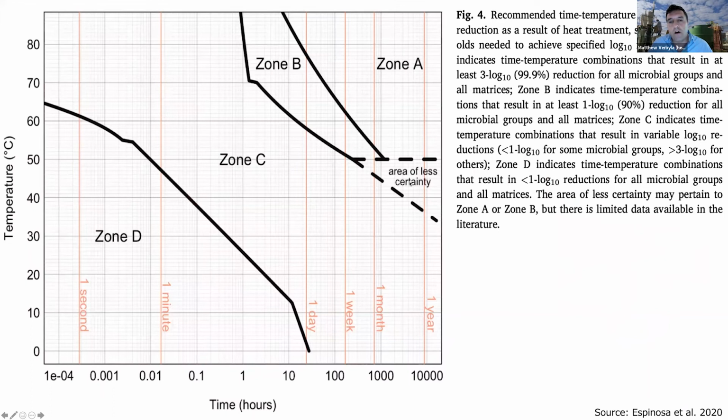So in order for all pathogens to effectively die off in a pit latrine, you need to achieve a combination of temperature and holding time, which can range from minutes to days to weeks to months to even years, depending on the pathogen type. So some pathogens, like bacterial pathogens, might die off more quickly than other pathogens like parasites, which can last for years at ambient temperatures. So this graph here just shows the relationship between temperature and time when it comes to pathogen die-off.